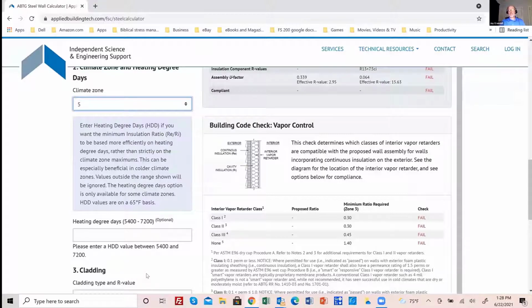But on the moisture check, it's quite precise in how to balance your exterior insulation amount to your interior insulation amount, so that you keep that wall, and what would be a condensation plane, warm enough that it doesn't see dew point and stays dry in the winter.